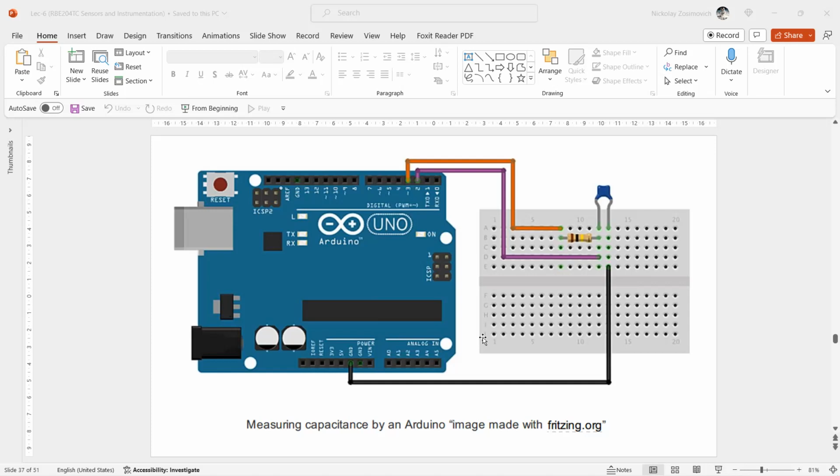This approach allows for a simple, albeit nonlinear, analog to digital conversion, which can be implemented using a single microcontroller pin. Since the nonlinearity is highly predictable, as it is a first-order RC network, the relation between measured time and input voltage can be linearized.